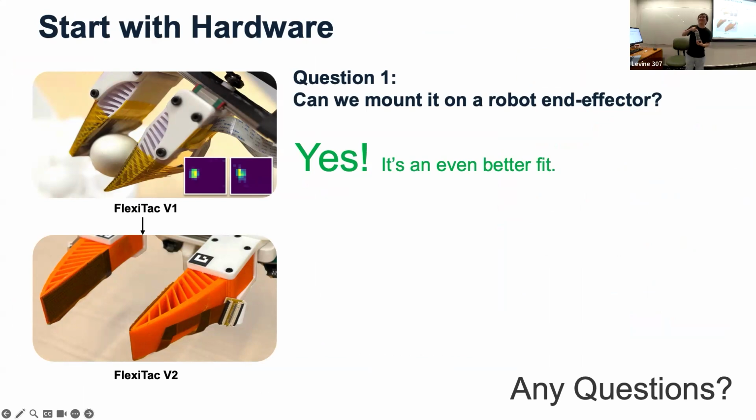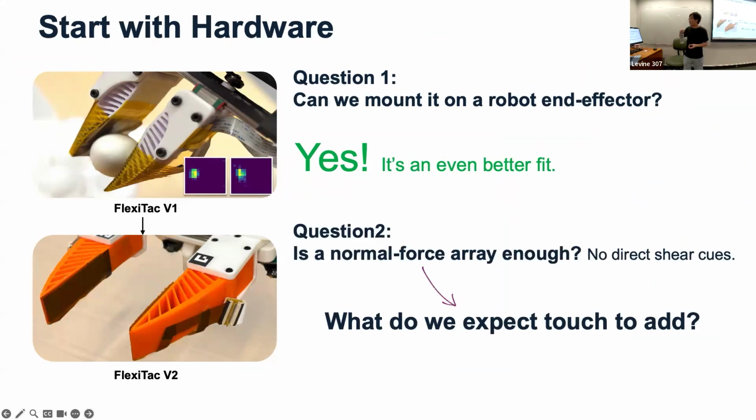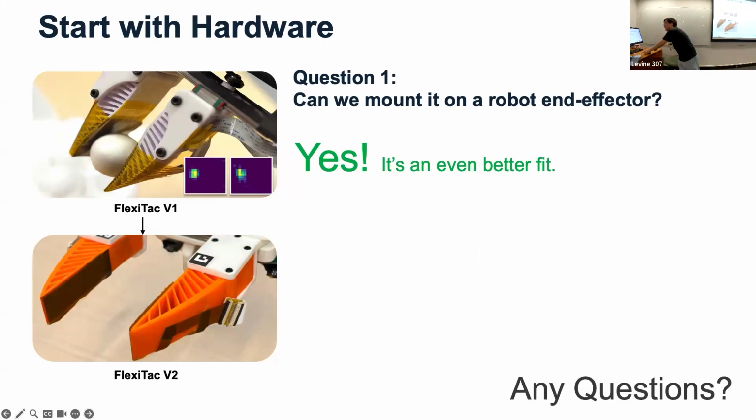Also, what's the force resolution of the sensor? For example, what's the lightest force that you can detect? Oh, I see. The lightest force we can detect is about 0.25. That can depend, because if you apply a very low force, there will be a lot of noise. So it's a trade-off between the noise level and the sensitivity. Sometimes we set a higher threshold to lower the noise.